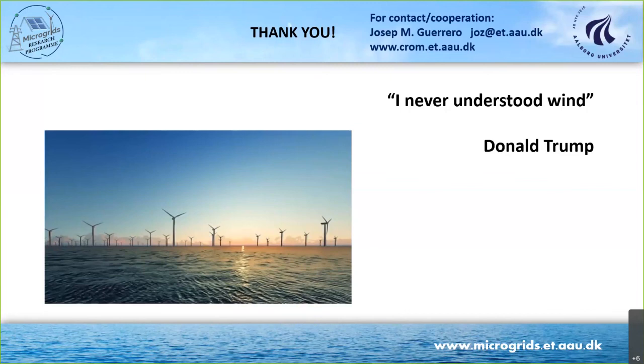Of course, this is a problem because if the speed of your rotating part goes down from 70% of the nominal speed, it will be very hard to recover again, and maybe your wind turbine will have to be shut down. So I would say that's the main problem. If we want to increase this virtual inertia further, the use of energy storage is mandatory. But right now it is going to be very useful if we want our wind farms to act as a conventional power plant, in the sense that they participate in voltage and frequency like the others. It will be a must.